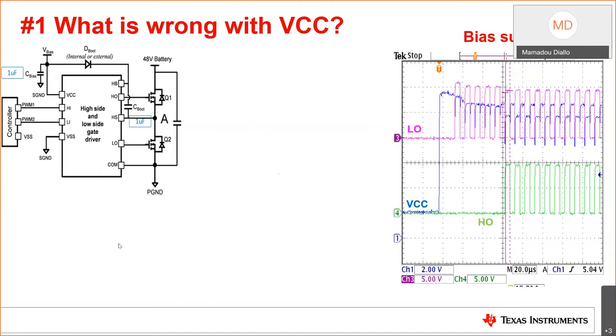Okay, let's see. Looks like we have most of you picking both B and C, which is the high ripple due to insufficient filtering on the VCC. That makes sense. That's a good answer. And also C boot and C bias incorrectly sized. That's also a correct answer. Notice on the schematic here, essentially C bias equals C boot, also equal to 1 microfarad each.